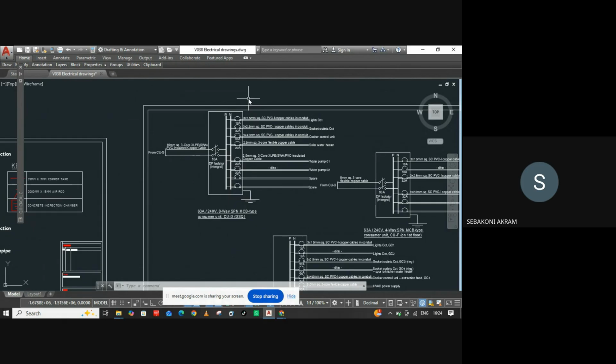Are we together? Yeah, load calculation. You have to calculate the loads, then find the size of the cable that can supply those loads, that can sustain the load. It is from the load that you select the circuit breaker.